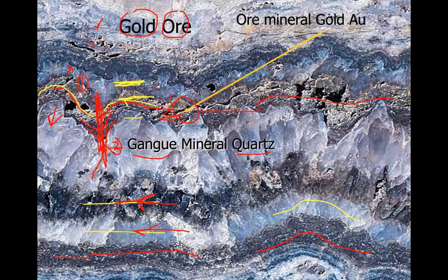So we have to do a physical method, a physical technique, to find out the extension of these layers, whether they are angled or horizontal or vertical or whatever it is, right? For that, you have to do some exploratory drilling, right? Yes, correctly mentioned, directly core drilling. So you have to do some exploratory drill holes. You have to dig some drill holes.